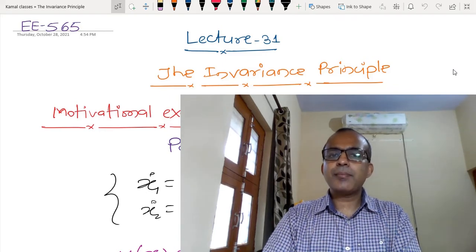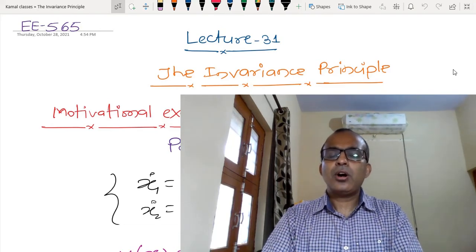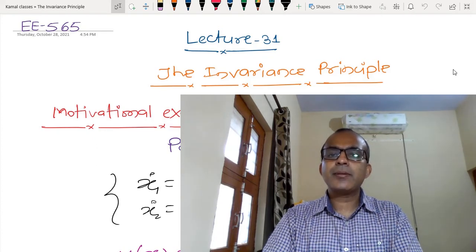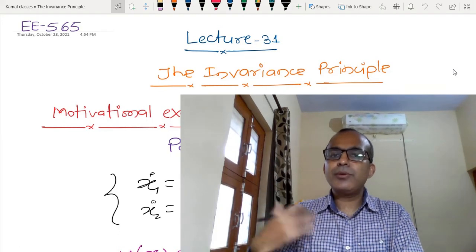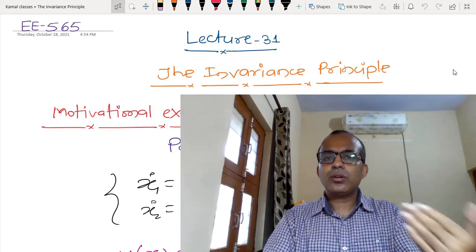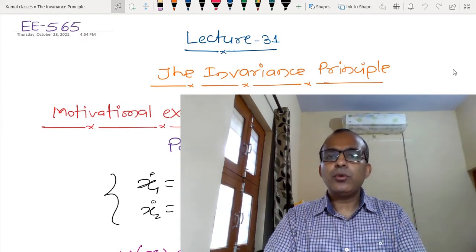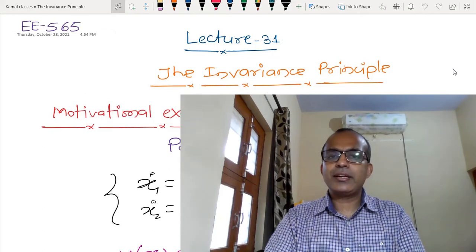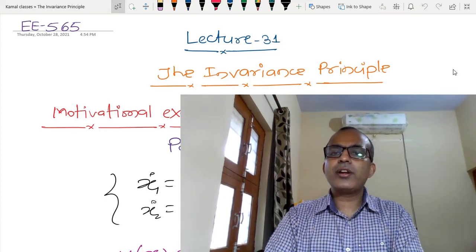What does it mean? Suppose the Lyapunov condition for stability, either stability or asymptotic stability, is somehow not satisfied. It doesn't mean that the equilibrium point is not stable or not asymptotically stable. One can only say that we have to develop some new Lyapunov function, because the previous Lyapunov function we developed for the analysis is not able to quantify the stability of the equilibrium point. But failure doesn't mean that the equilibrium point is not stable or asymptotically stable.